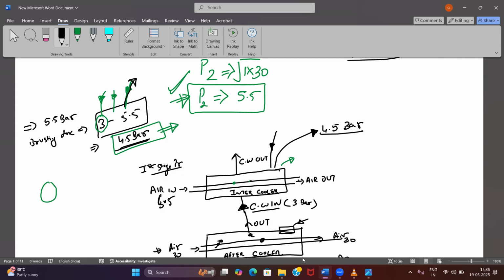It has happened in one of my vessels actually. I was not on board at that moment, when I was junior engineer. I came to know from my previous third engineer what they did. They didn't have a spare bursting disk, and the bursting disk burst. So they figured out by doing tests which tube is leaking. They plugged the tubes and then fixed it back. But they didn't have a new bursting disk. Once the bursting disk is burst, you cannot reuse it. You have to use a new one. So he put a metal plate there. Now you don't know at what pressure the metal plate is going to burst.